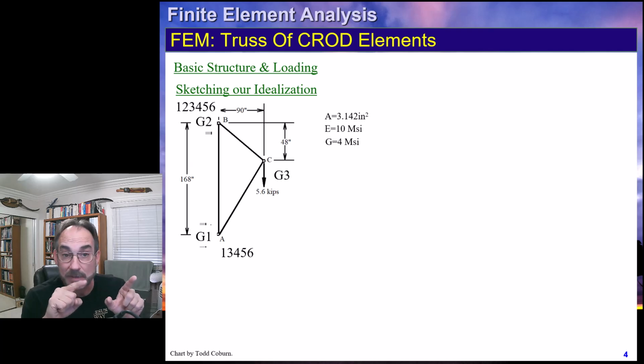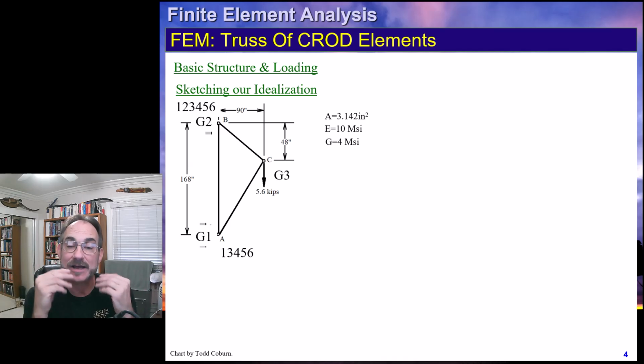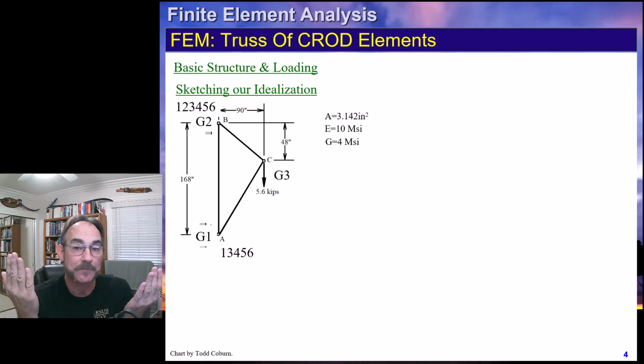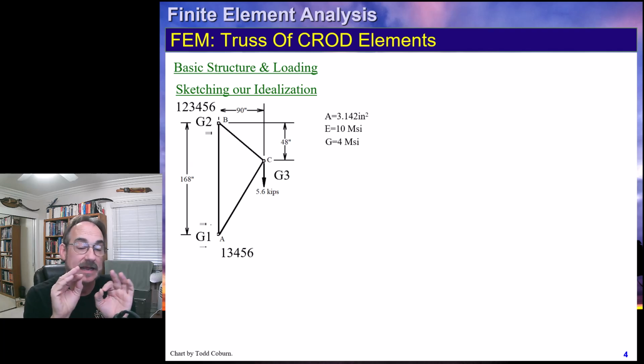If you look at this model, we're going to model this with 2 rods, and rods can't resist twist. They can't resist out of plane rotations, only rotation around the element. That means putting these fixities doesn't change anything because the rod element can't transmit those. So fixing these removes the chance of a fatal error, but also allows it to behave as it's supposed to behave. So 4, 5, 6 has no effect.